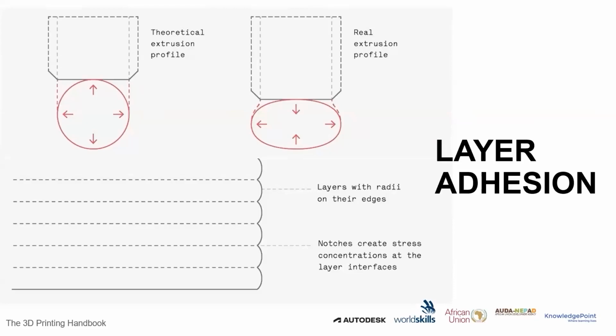So you are having an error from your design, because the design is one shape but this is how it's going to come out. You see the profile moving in this direction, so it's not coming out as designed. You see this error margin because of layer adhesion. It's important to know that layer adhesion, or bonding, is an important part of the printing process. Our filament is extruded, and it needs to bond and solidify with the previously printed layers to form a solid, cohesive part.